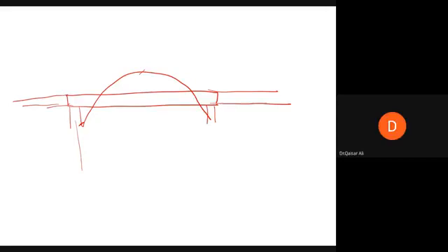So you can see that near the support, the positive bending moment becomes 0 and negative bending moment is introduced. So if there are 4 bars here, you can curtail or reduce some of these bars near the supports. You can make 4 bars into 2 bars, cutting 2 bars so that you bring some economy to the project. Then, because there is negative bending moment, maybe 4 bars will be required here instead of 2 bars in this location. Ahmad, is it clear now? Yes, sir.